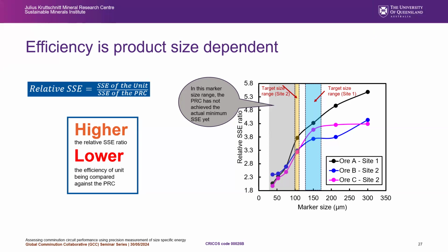What sort of precision are you getting on the gap between the rollers? Considering how you're adjusting them, playing bearings, concentricity, and all that. Yeah, so I think I have added the number in my thesis, but off the top of my head, somewhere plus minus, especially in the fine size range, 20 micron. Was that 20 micron plus minus?